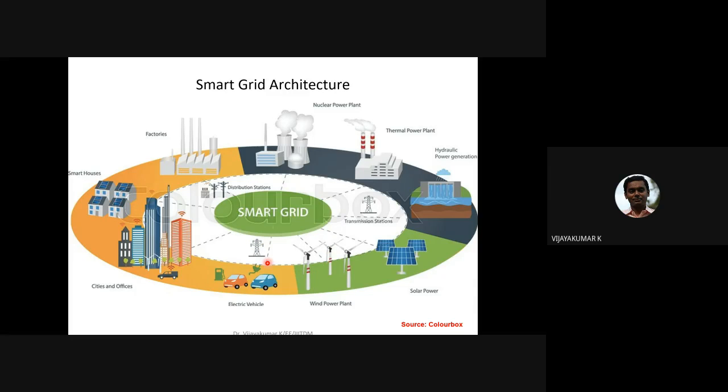How? It's very simple. Earlier also you used energy storage. By aggregating all the electric vehicles in the buildings, you can aggregate some energy storage, and that energy storage gives support to your large scale energy storage. That means you need not go to that capacity. Instead, you can reduce the capacity of the energy storage, so that you can save the cost in the smart grid system.